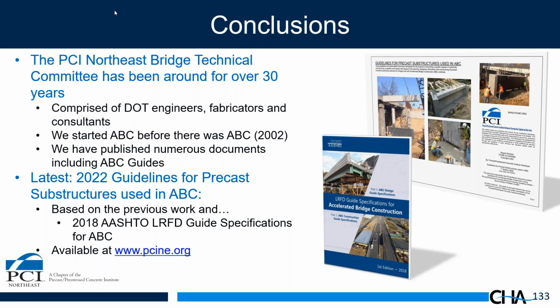Okay. What are some rules of thumb for precast substructure connection details? My rule of thumb is, one, take into account tolerances. Tolerances are really important. And two, work with the owner to pick the right connection for your bridge. Make sure the owner's okay with it. That's my rule of thumb. Okay, they all work. Also, talk to the fabricators. They'll provide you input on connections, because they're going to have to construct it.